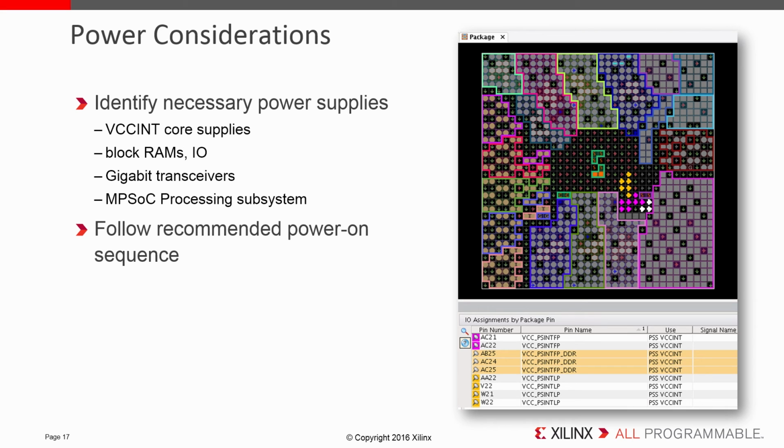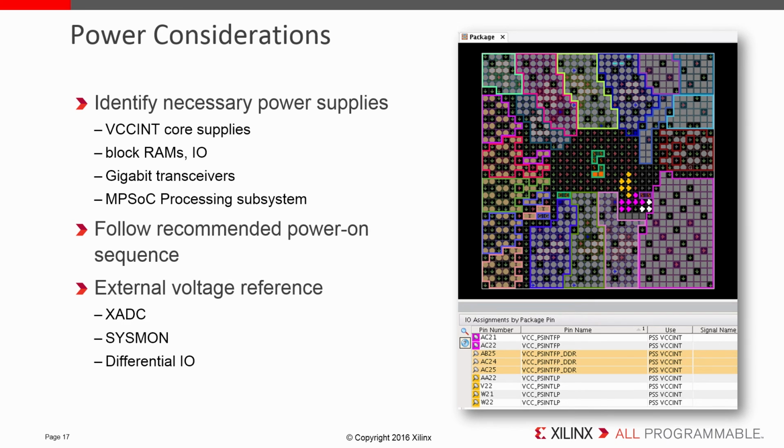With so many different supplies powering the device, it becomes important to follow the correct power-up sequence. And note that an external voltage reference is required in some cases, such as when using the XADC or system monitor, or a differential I/O.